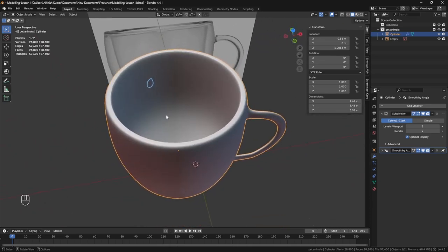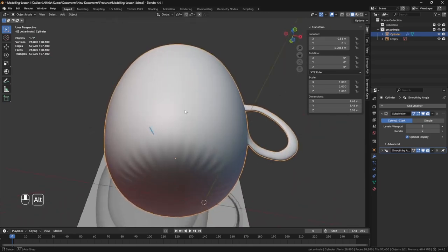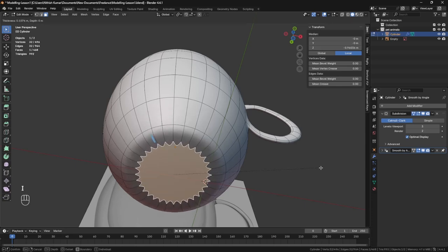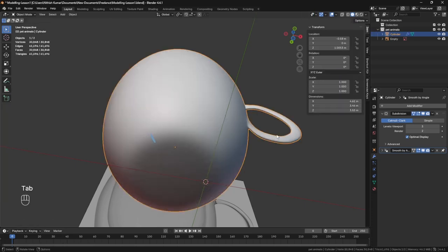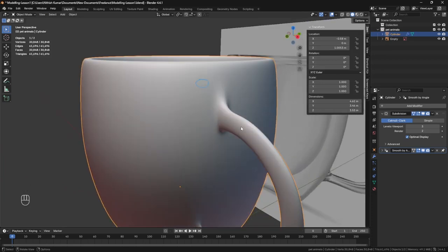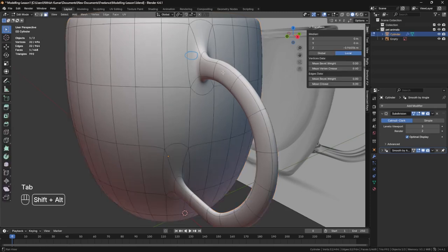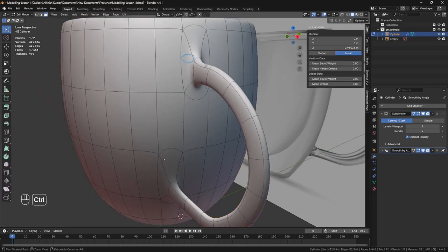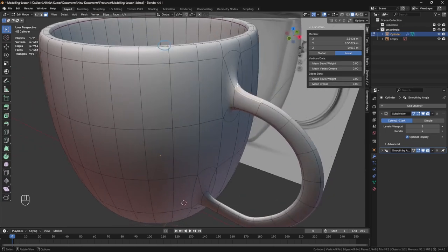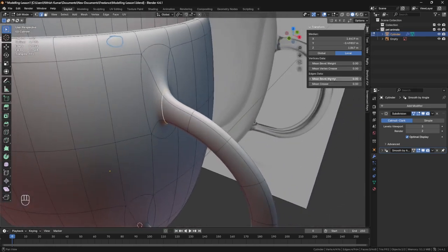Now this one is fine. It looks okayish. Let me also decrease this. But the handle of mine looks too weird. What I can do is either expand it as a whole, or go to edge selection mode, select the edge, and increase the size like this, maybe.